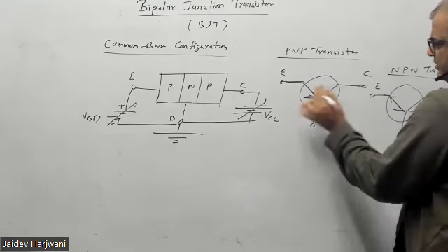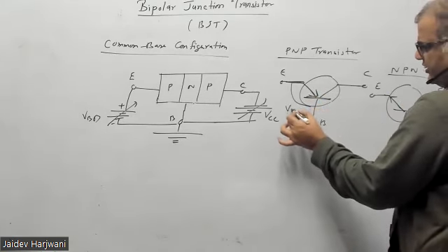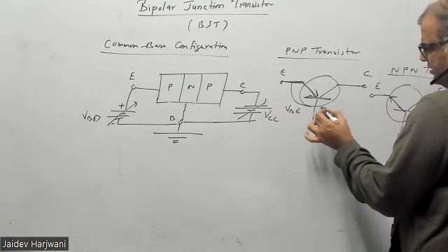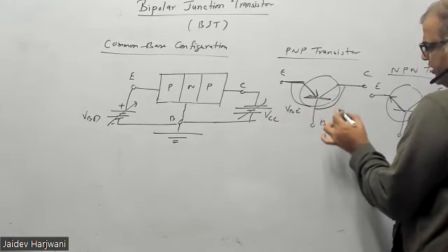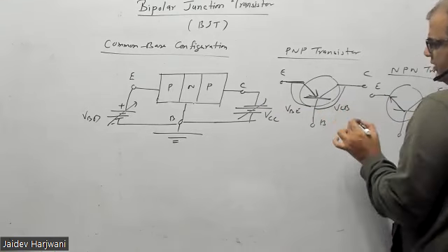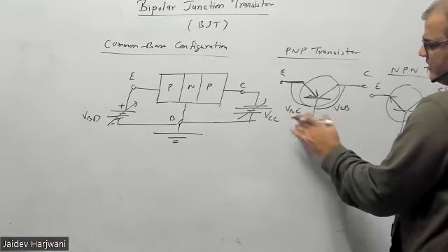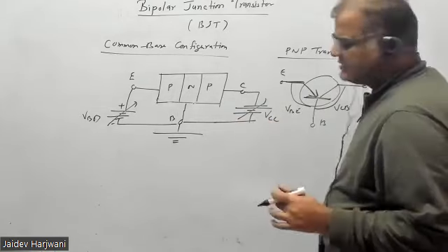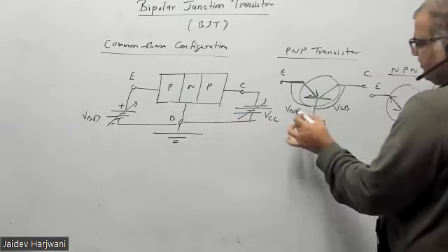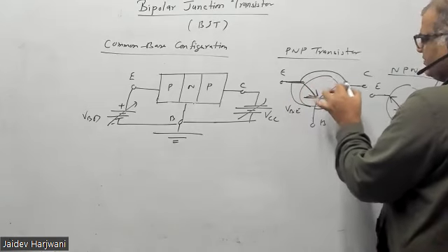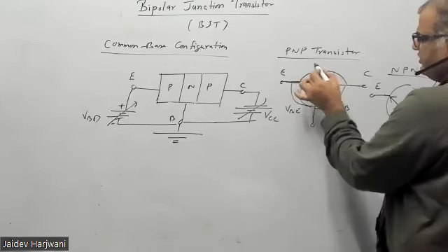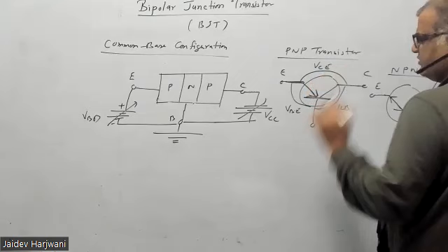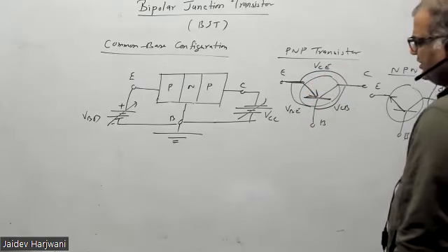So this is VCB. This is basically your voltage drop VBE, and from here to here the voltage drop is VCB, okay. VB with respect to B, so VBE positive, so you write VBE, you can write VEB also, and VBE plus VCB, the voltage between E and C is called VCE or VEC, whatever you want to measure, difference of voltage, okay.